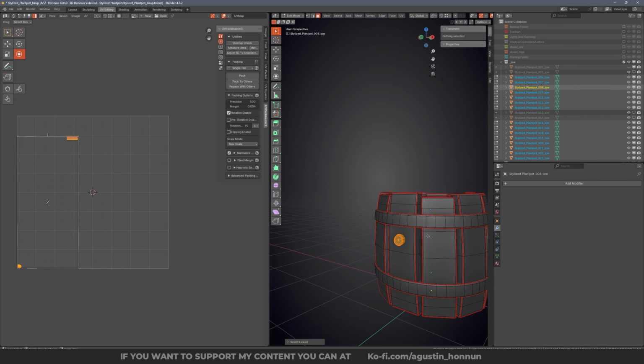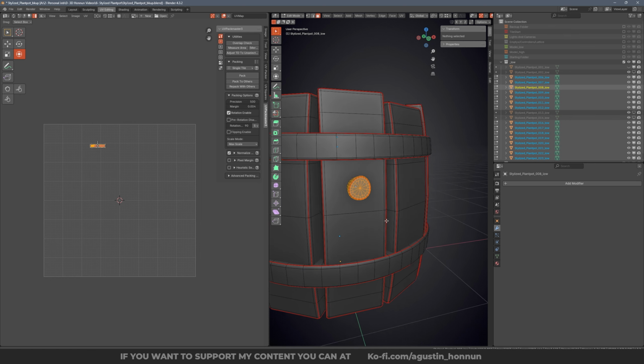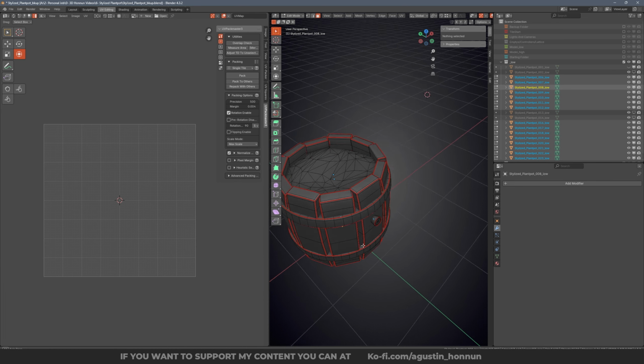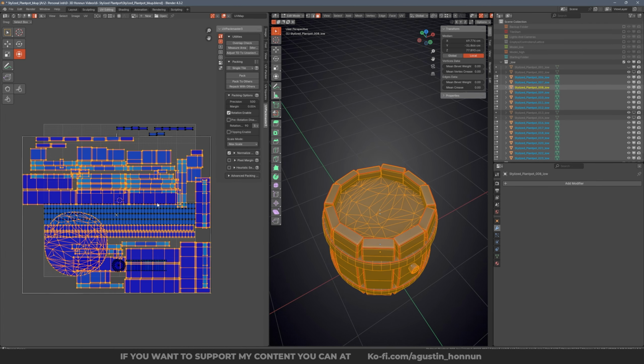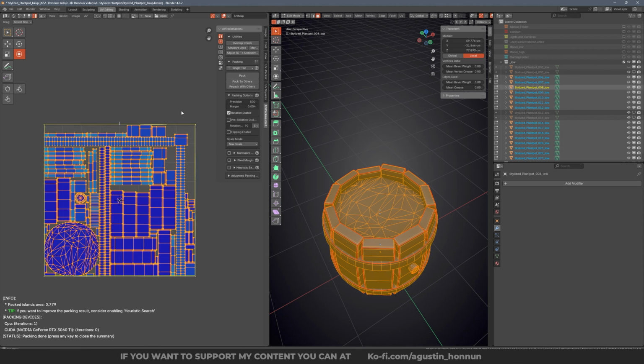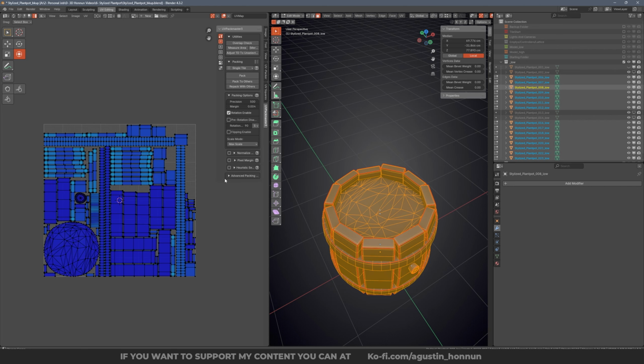And also for this part, since this is a very small piece, UV Packmaster may decrease the priority of this a lot because it's a small piece, but I want it to have a more decent quality. So I'm going to increase it. Okay, the rest is fine. So now I'm going to select all of these, disable normalize scale and pack. So it will pack this using the scales I made before.